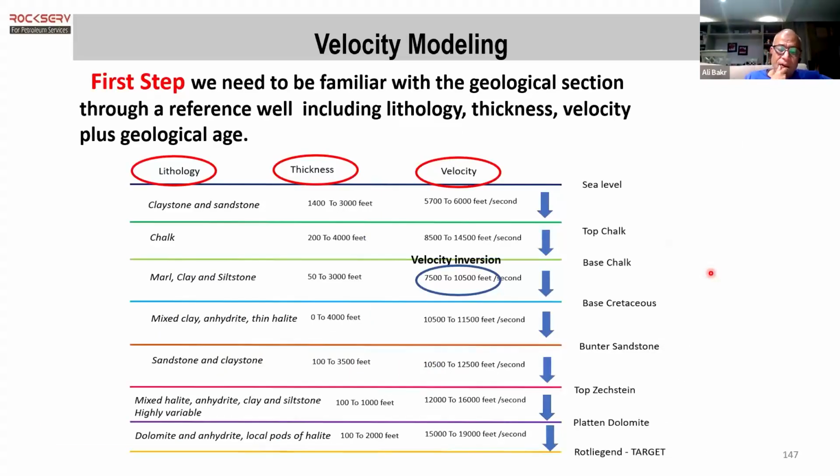In order to do a velocity model, you have to go through more or less 3 or 4 steps. First of all, you have to analyze the geological sequences that you are talking about. You have to divide them into different intervals according to what? According to the well data. So, as an example, you go through a cross section through the wells, and you come up with the sonic displayed at each well, and look at the interval where your velocities are variable, where they are changeable, and pick up those intervals. And usually we call those intervals flags for the velocity, where at that interval the velocity dramatically changes, or you can see them increasing, taking into consideration the assumption that the velocity increases with depth.